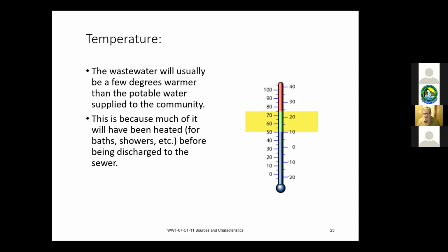And if you think about it, it kind of makes sense. Your bacteria and organisms are living, breathing things. It's like when you go outside in the summertime when it's nice and warm out, you've got a t-shirt and shorts on, you're running around and very active. The organisms are exactly the same way. When you get to the lower temperatures, people are putting their parkas on, they're not going out as much, they're staying inside, they're not as active, and the biological component of your plant does the same thing. Everything slows down at a lower temperature.